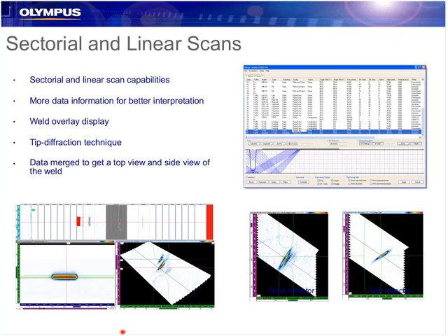So here we see views, if you've used an OmniScan or Focus LT, more like what you might be used to looking at. So we have a C-scan as well as an S-scan with a weld overlay of the joint, and again a linear scan with the weld overlay as well. So often these are used for extra information or added information to be able to discern geometric reflectors or do some tip diffraction sizing. So the zones are very good, but having this added benefit in some cases, the ability to add sector scans and electronic scans selectively, could be very good for certain joint designs.